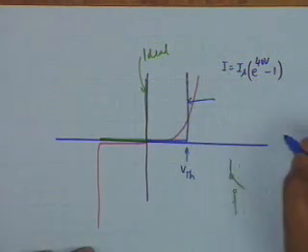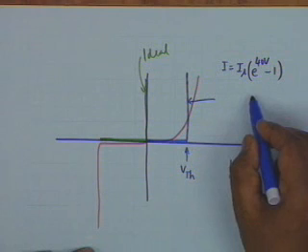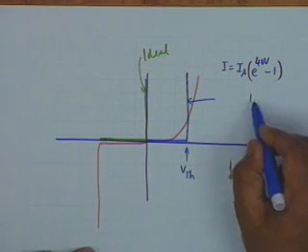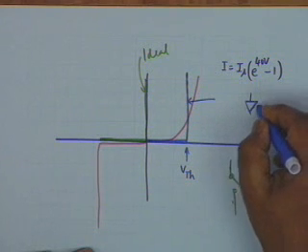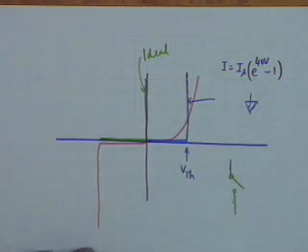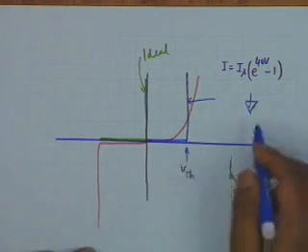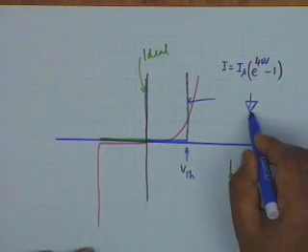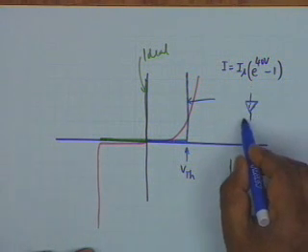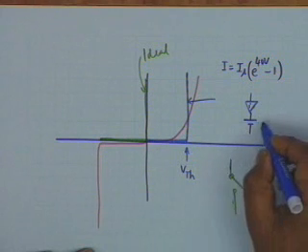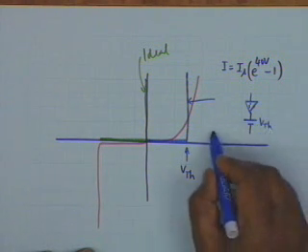Now this curve can be approximated by an ideal diode. Now we shall use the symbol I inside to denote that it is ideal, all right. An ideal diode, that is a switch, but this diode does not conduct till this potential rises to 0.7 volts. So we have a battery which is equal to the threshold voltage.